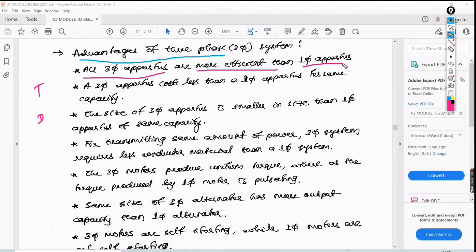If you have a motor rated around 5 kilowatt, just an example I have taken, 5 kilowatt means 5000 watt. Whether it is active power or reactive power, which power is it? Active power, because the unit is watt. If the load of 5 kilowatt is supplied with single phase power supply, the same thing can also be supplied with three phase. But the efficiency of this machine is good for three phase power supply because of least losses. If you connect it to single phase, then obviously the losses will be higher because of more current. Why? I will tell you.